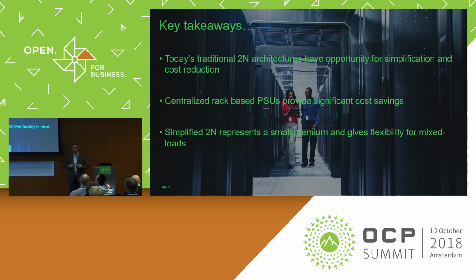Fantastic question. So let's talk about two things with lithium ion, and actually we have to talk regionally. I can go from some experience from Schneider Electric's perspective. Two years ago, we launched a lithium ion solution for larger UPSs, so large lithium ion to replace large format VRLA batteries. People started to switch over when they knew that after the first battery replacement, you were better off. The TCO was within 5 years, because the lithium ion is going to last 10 years, VRLA maybe 5 to 8 if you're lucky.